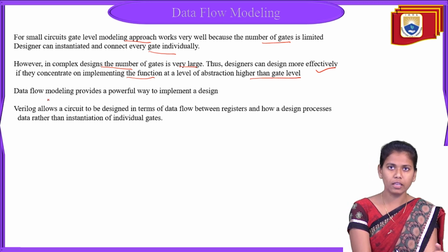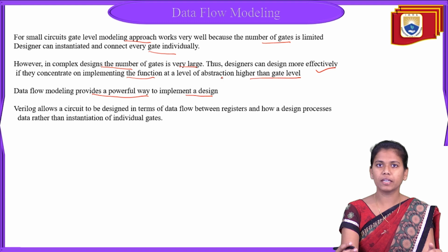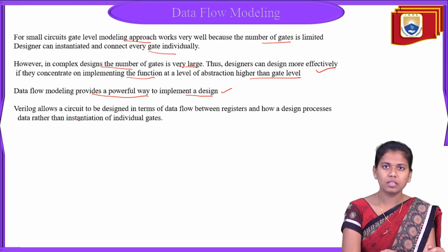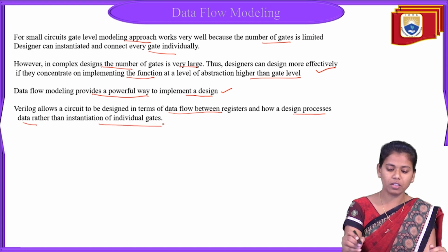Data flow modeling provides a powerful way to implement a design. To overcome certain constraints, designers go for data flow modeling, which provides an easy, powerful way to implement a design. It is very easy to design a complex module using data flow modeling. Also, Verilog allows a circuit to be designed in terms of data flow between registers and how the design processes data, rather than instantiation of individual gates.